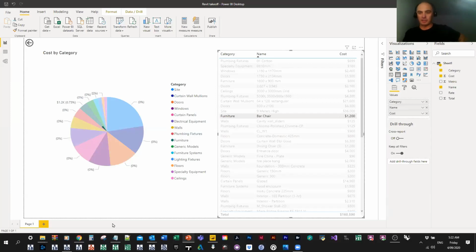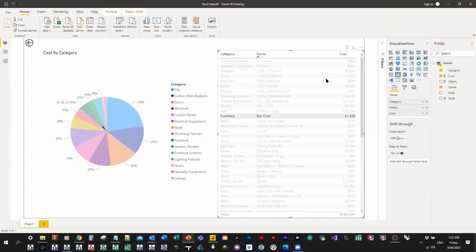Mark, is it possible to create a duplicate of the cost and then calculate totals for that calculated value? So you could add a shared parameter on a project basis and then populate it there. Could you not just create another parameter that just equals the cost, and then calculate totals for that? Do you mean when I was struggling with the count section, or when you're struggling with having both the calculate totals and the unit cost and the total cost as 2 columns? You just create another calculated value that equals cost and calculate totals for that.